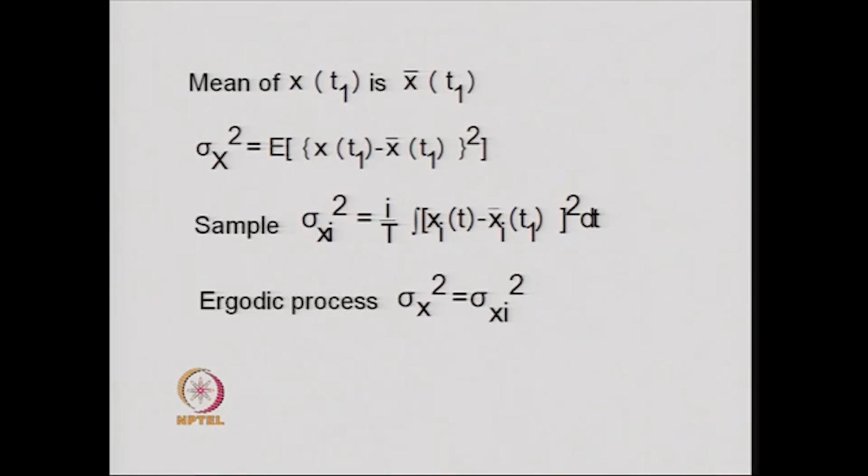It is really hard to get exactly an ergodic process in reality, but for solving many problems in random vibration, we assume the property of ergodicity, because the assumption of ergodicity simplifies the analysis procedure. So, in our case also we will assume that the earthquake process, or the future earthquake, is not only stationary, but also ergodic.